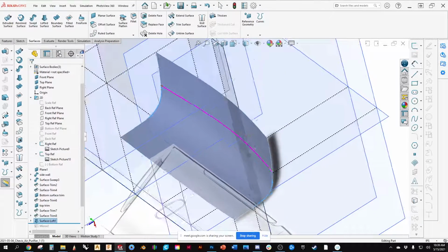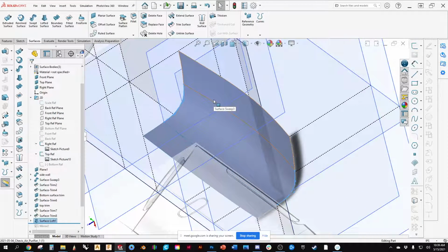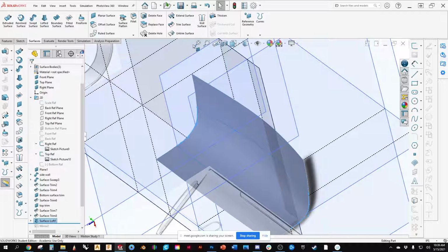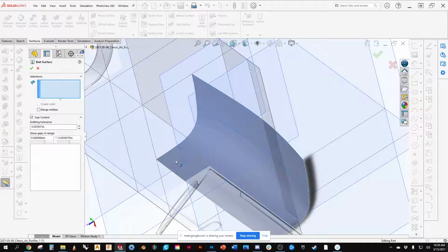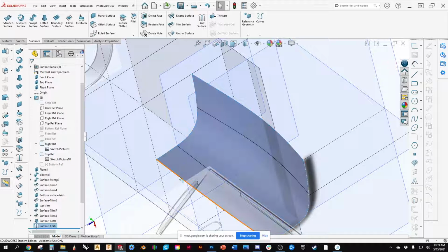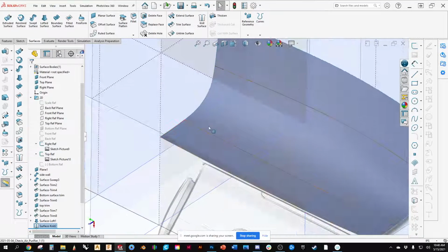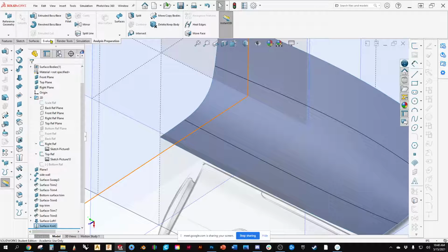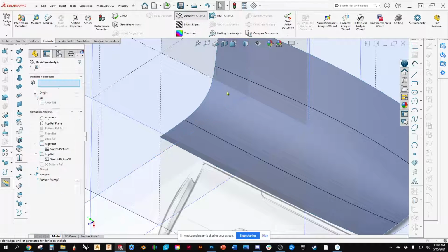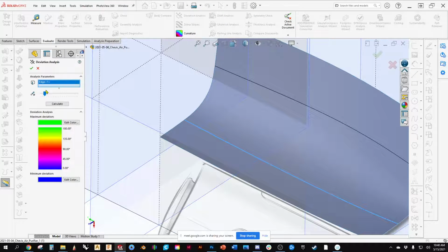And then what we're going to do is, again, we may not want to knit this 100%, but again, we're going to build, evaluate, and refine. So I'm just going to quickly knit it. And you can see I've got solid black lines. So I have tangent lines turned on to be phantom, which means that if I come in and go evaluate, and check angle deviation, this isn't going to be nice.